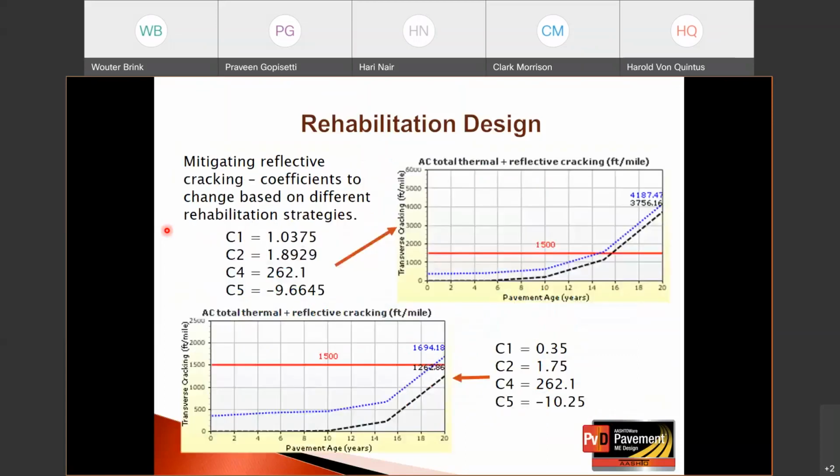However, with time, some agencies that have used interlayers or seal coats within their own practices and have done calibration and have updated the global reflection cracking transfer function with the calibration coefficients, have found and shown differences between those asphalt overlays with and without different mitigation strategies.